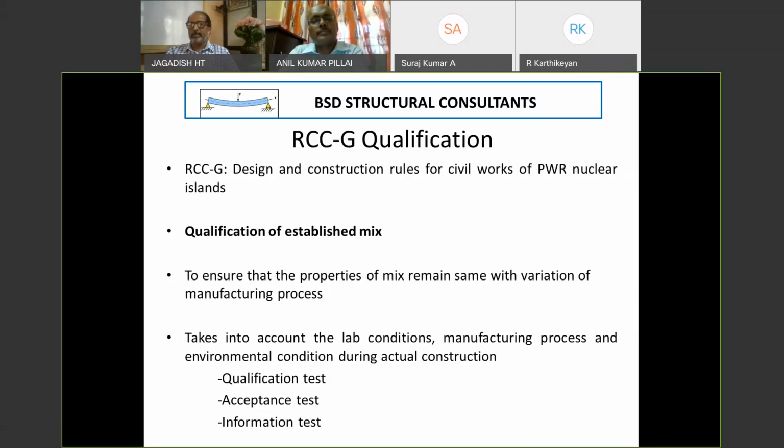In a boiling water reactor, the reactor coolant boils within the reactor, steam is produced, and the steam goes to the turbine. There were a lot of problems in a boiling water reactor. Pressurized water reactors. Now, in pressurized water reactors, there are again two types. We have pressurized heavy water reactor and pressurized water reactor, or normal water. In India, we are using only pressurized heavy water reactors. We're not using PWR. PWR is not Indian technology, but we have imported PWR for Kudankulam from Russia. So today we have PWR also, and there are some more plants coming up in PWR in the future.